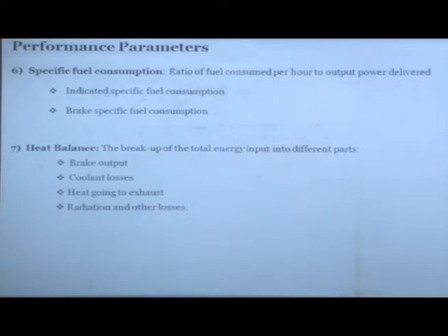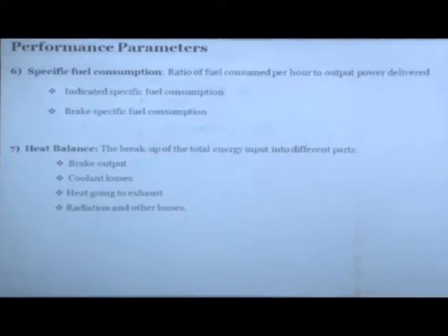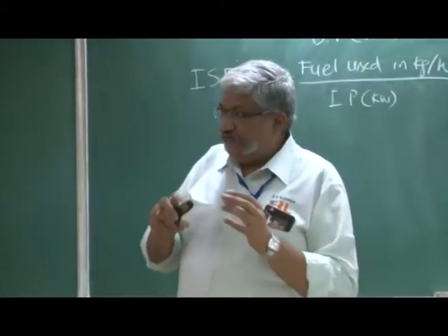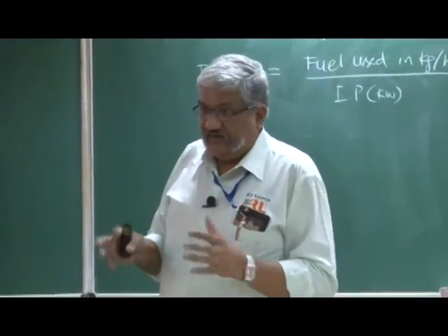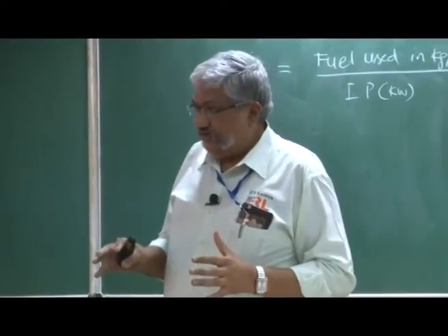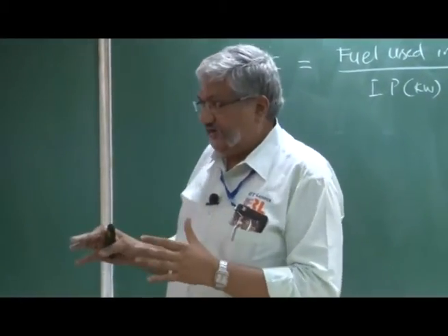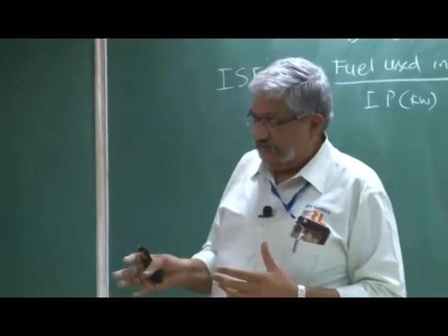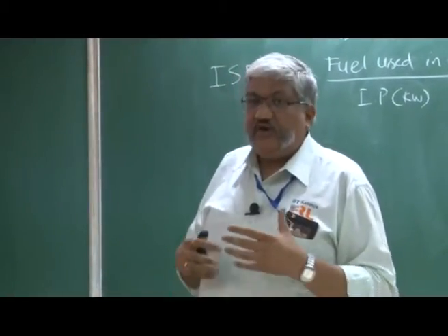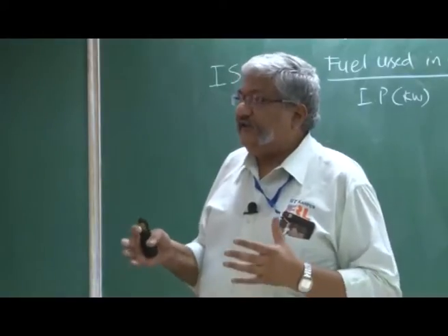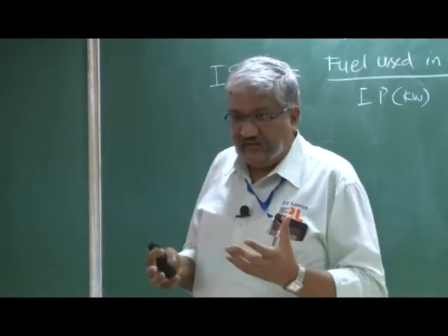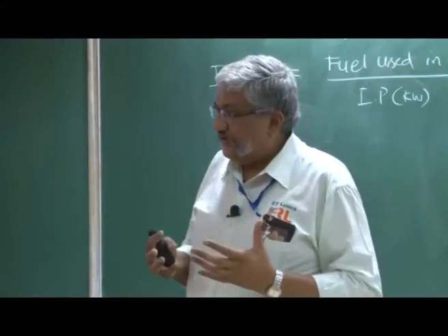So if you look at the energy, where it is coming from, the only source of energy in an engine is fuel, combustion of fuel. And where is it going? It is going first and foremost into useful power production, because ultimately that's what you want. And what are the other sinks? It is going into coolant, because the engine requires coolant in order to keep its temperature under control. So there is some heat that is being lost to coolant. Radiator is there that is finally losing the heat to the air. If you look at the exhaust, a significant amount of heat goes into exhaust, because exhaust gas is hot. So that also takes away a lot of heat.